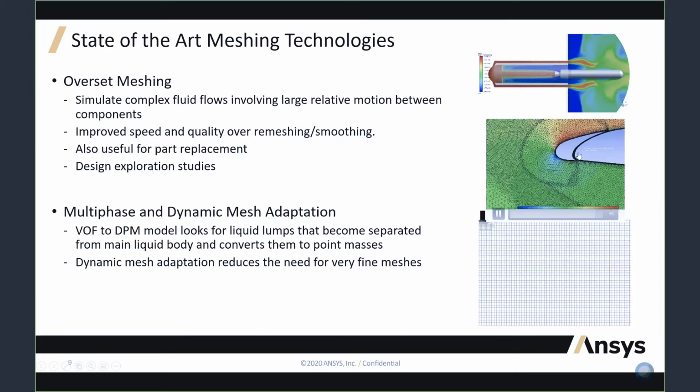Here in this example, we have an example of the overset meshing technology used on a complex compound wing. Here you can kind of see the overlay of the two meshes. So we have one mesh for this region here, that leading edge, and then a separate mesh for just the entire domain outside. And really, with the interpolation, one mesh moves relative to the other, and then the code automatically takes care of interpolating the solution in between them.